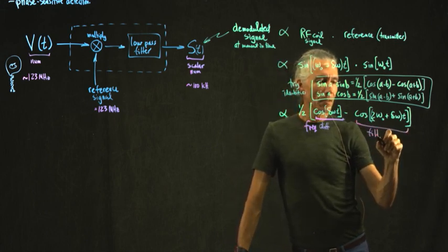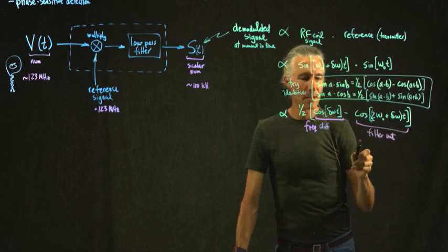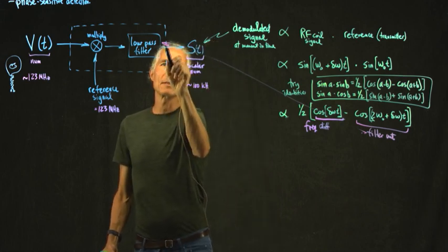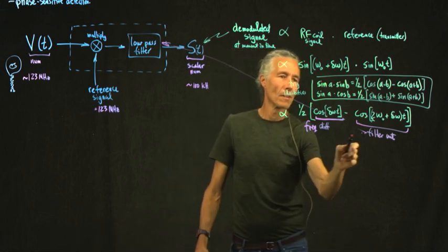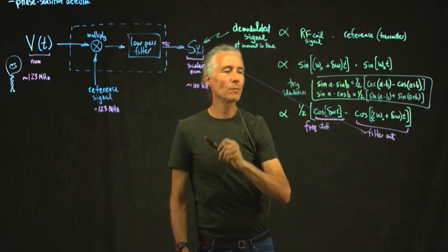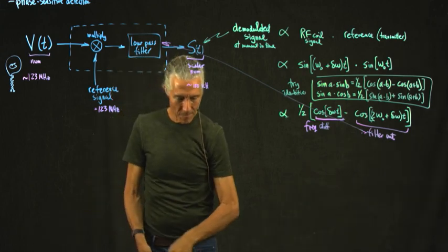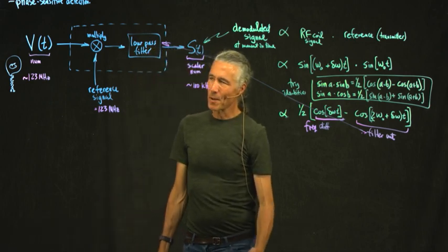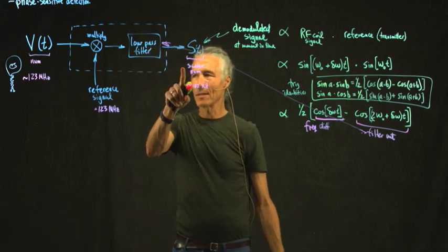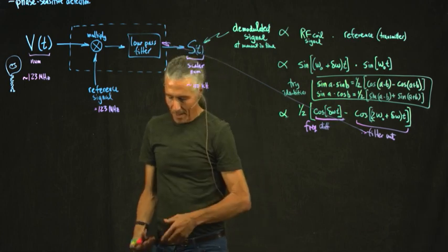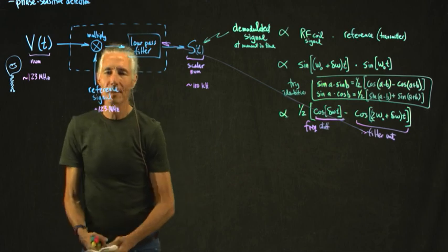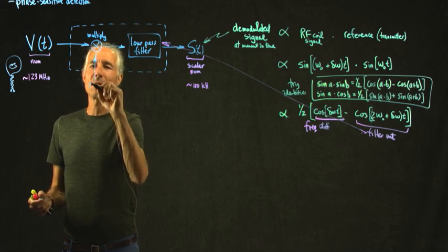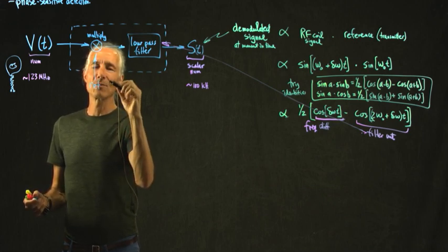So that's the one that's filtering this out. So filter out that one. We just want to keep the frequency difference. That's the bottom line. But we're not done yet, because obviously we've still only got one stream of numbers here. So how do we get the second stream of numbers? To get the second stream of numbers, we basically just multiply with a sine and a cosine.